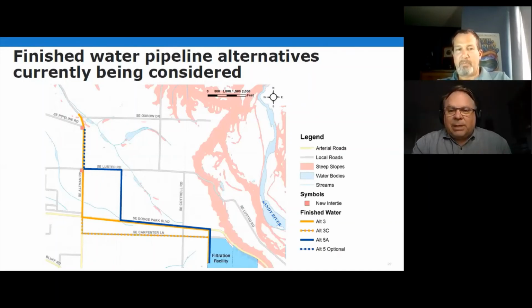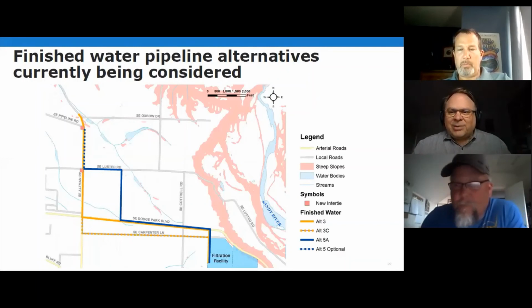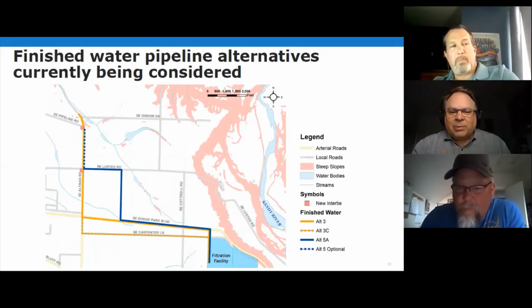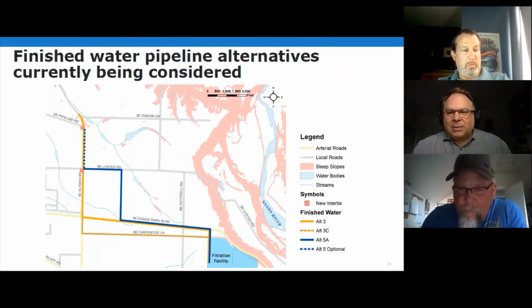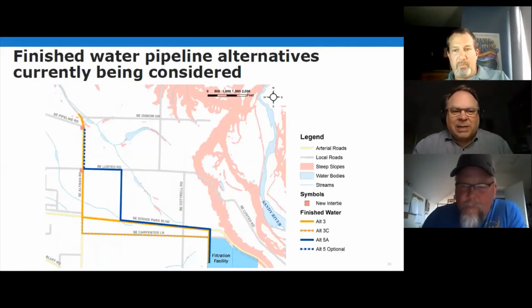It doesn't mean that we're going to be replacing all the conduits from Headworks into town. Many of the improvements are simple improvements to either the ground around the existing pipes or the joints on the existing pipes that will be done over a number of years. So we're looking at between 30 and 50 years in an effort to seismically restrain these pipes. So we're chipping away. As Ken pointed out, it's 25 miles into town, there's 75 miles of pipe. We're doing bits at a time. What we're able to do here with this project is replace, what is it? 4 miles. 4 miles times 3, so we're replacing 12 miles of that pipe.